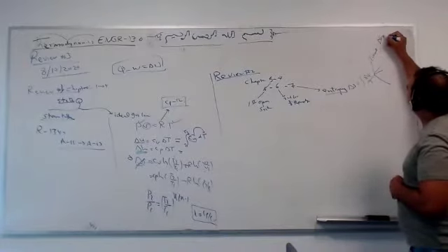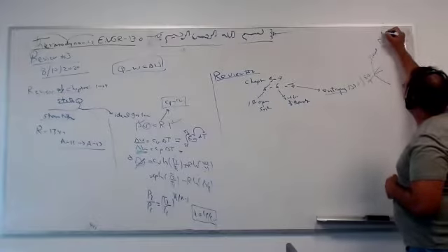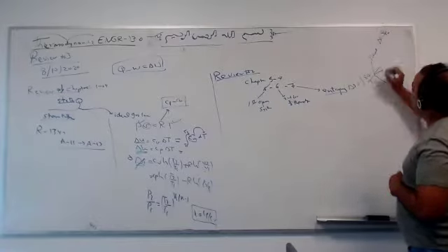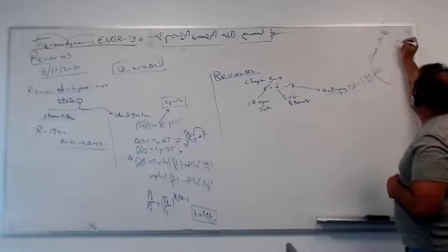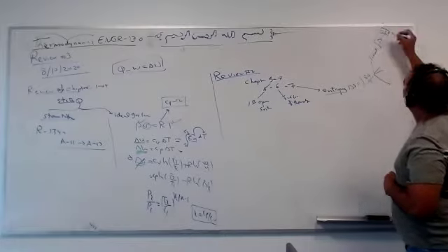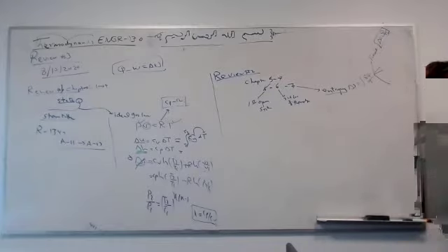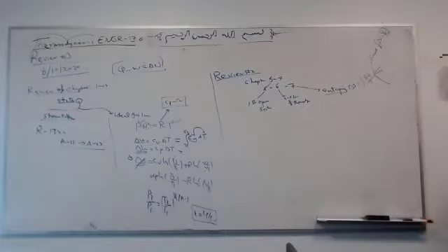Delta S equal to what? 0? No, Q over T, where temperature is constant and can be taken out, so just delta Q over T. This usually happens for a thermal reservoir, not thermal equilibrium. It means the surroundings: you dump heat, but the temperature does not change. So it's not isothermal, it's called an isothermal reservoir or surrounding.